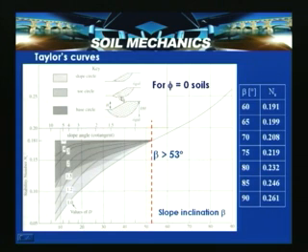So, here different types of circles are passed, like slope circle, toe circle and base circle. The zones are indicated here. This is valid for beta less than 53 degrees, where the depth factor cannot be ignored, but beyond that, the depth factor will not come into picture. So, this particular curve is for phi u equal to 0 soils, that means these are for the undrained condition, that is Cu, purely cohesive soils or saturated cohesive soils.